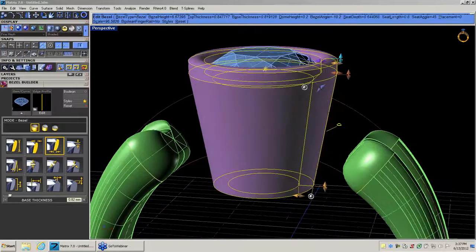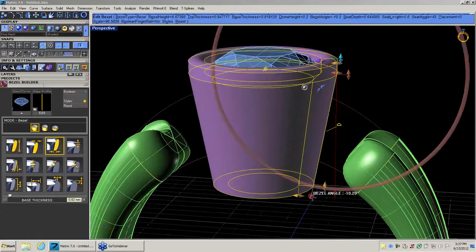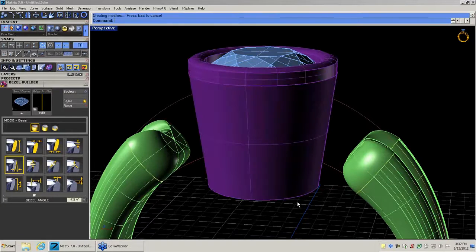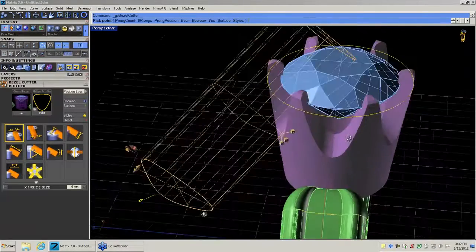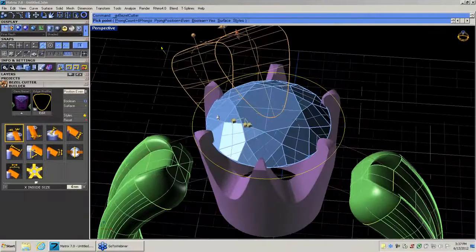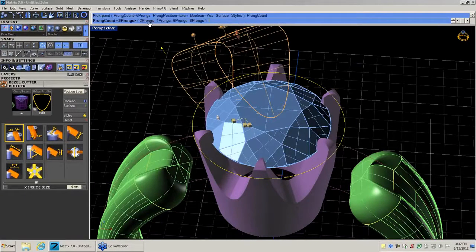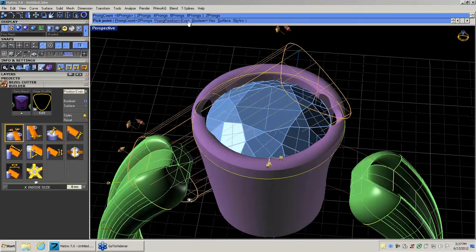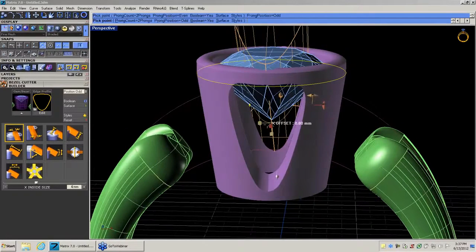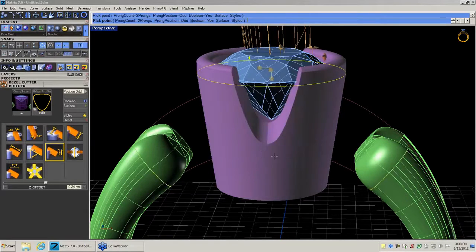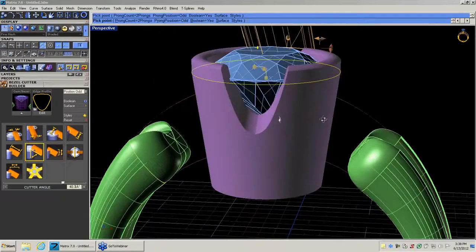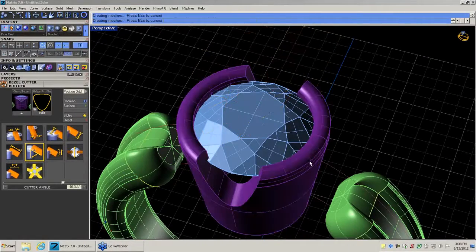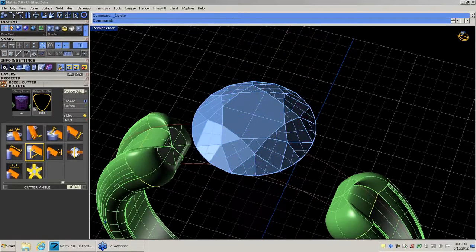Things that you're going to know, and just like before, there's our library, so we have different shapes that you can utilize there as well. I'll show you this tool real quick, but if I select the bezel and hit F6, I hit bezel cutter, it brings up a cutter that I can then turn this bezel into a head, and I can choose however many prongs I want, whether it's going to go this way or whether it's going to go this way. And again, knowing your jewelry and knowing how much metal we need underneath here to make this thing stable is critical if we're going to go in and do some sort of half bezel. So understanding jewelry, once again, you have to know manufacturing.